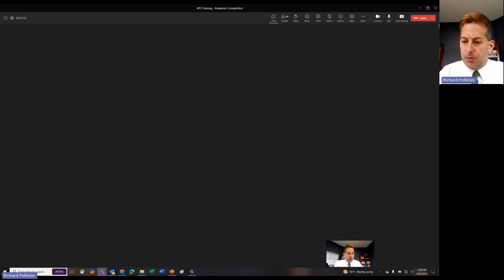In optimization mode, can we see the previous value of a variable and compare it to the current value? Also, can we add a step change along with lower and upper bounds? Okay. You would want to take a snapshot first before you run the optimization, and that would allow you to revert back to the snapshot and see the previous values. And you can also take a snapshot after the optimization runs, so that way you can see the optimized values. And then you can do a comparison between the two for the key properties that you're interested in.